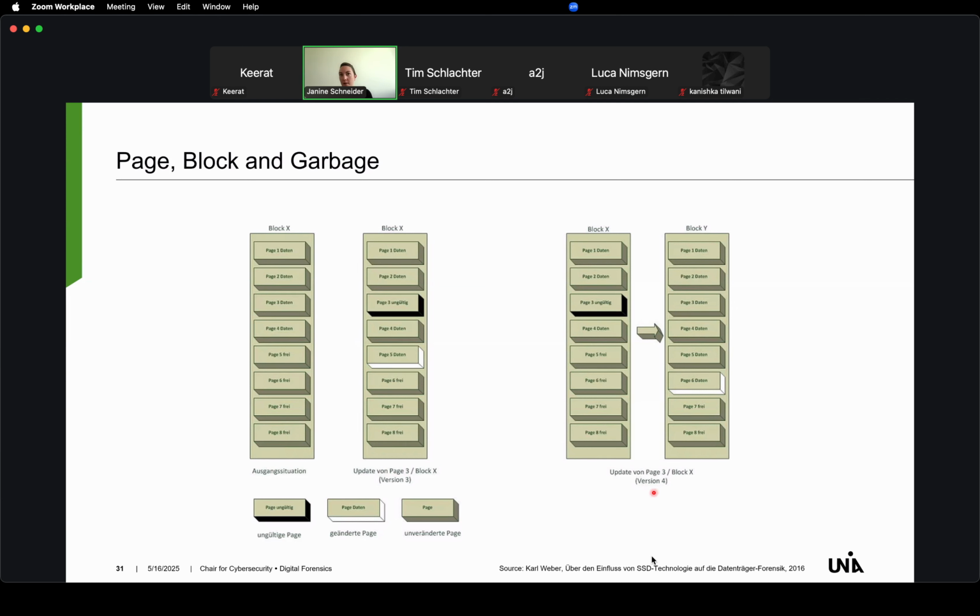No, for strategy 4, you don't copy the block. You take a page from your block and write your updated data to another page in another block, and then bind the LBA address again. I think you mixed up strategy 2 and 4 a bit. But is it now clear?